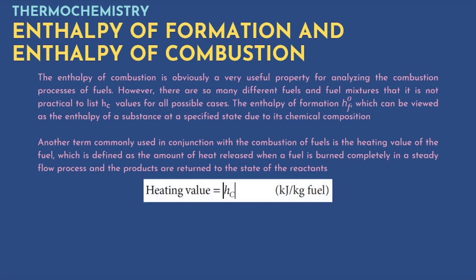The enthalpy of combustion is obviously a very useful property for analyzing the combustion process of fuels. However, there are so many different fuels and fuel mixtures that it's not practical to list h lowercase c values for all possible cases. The enthalpy of formation, HOF, can be viewed as the enthalpy of a substance at a specified state due to its chemical composition.